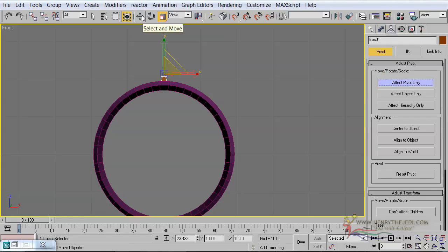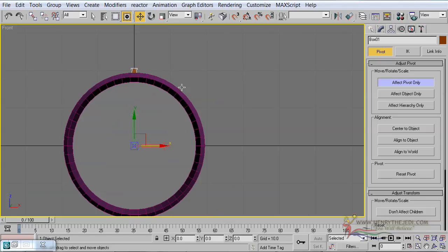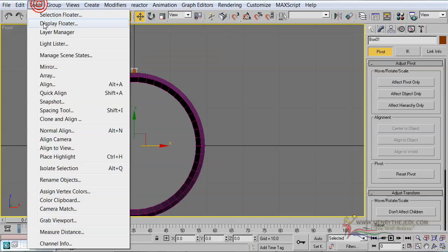and then we're going to select the moving tool, and then we come in here in these boxes, and then we're going to turn each of these values here to 0. And by doing that, as you can see now, the pivot point of the box is sitting right in the center of the eye. Why? Because the eye needs to be duplicated along the radius of the eye. Okay, so the main point was to adjust the pivot point and move everything to 0. Okay, and then we can actually unclick that box, and now we're going to go to tools, array.